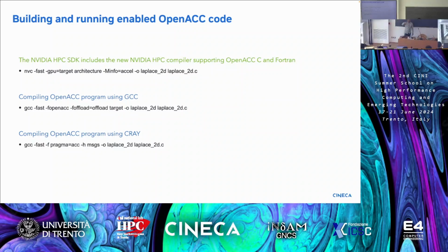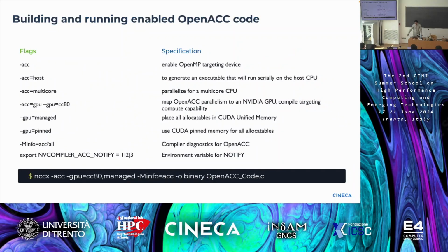If you just load the module on Leonardo and run the nvaccelinfo command, you can see all the specifications of our GPU hardware and what it supports. Does it have unified memory? Yes. What compute capability it has, what warp size we have, the streaming multiprocessor, all the information you can read yourself. So this is where you can compile for this specific hardware. But there is an additional flag, that is the one I was saying.